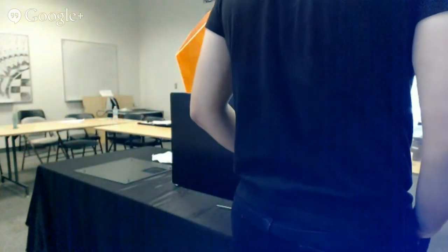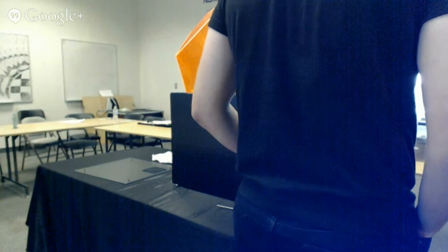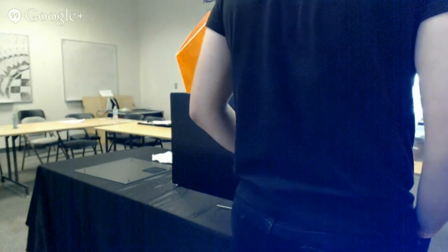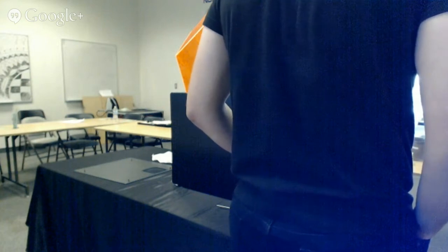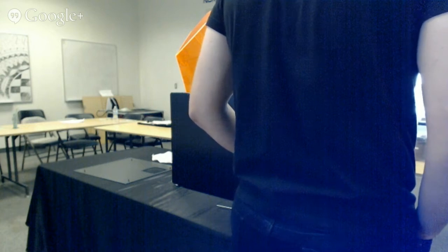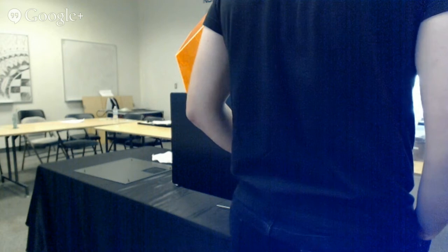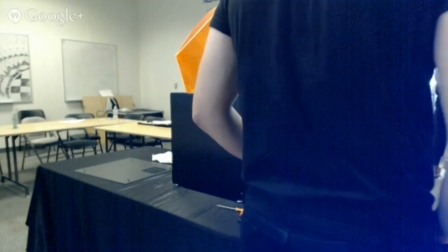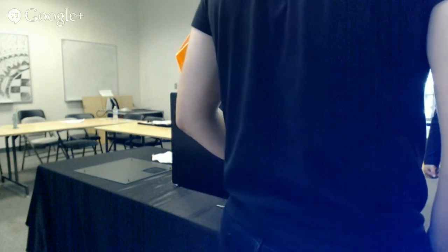This is possible because this part, by nature, is all angled, right? This part, when printed in this orientation, doesn't have any vertical surfaces, so it's no problem, right? It's not an issue of orientation, just how many vertical and horizontal surfaces do I have? Printed like this, I have very few to no vertical and horizontal surfaces. There probably was support. There had to be support to the chin.